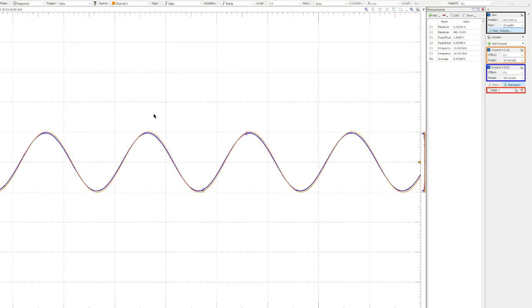So these are my waveforms for the previously shown circuit for scope 1 and scope 2. Orange is V in, and blue is the V output. Immediately looking at this, you can see that both V in and V out are practically identical. For the most part, they overlap each other, which is one way of proving linearity. There are two other ways that I will show in a bit, but first, here are the measurement values.